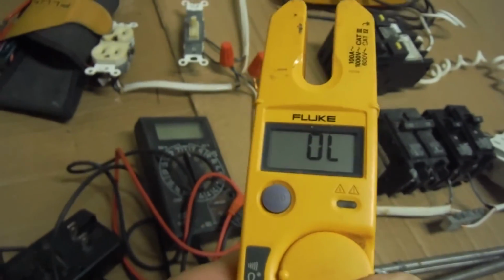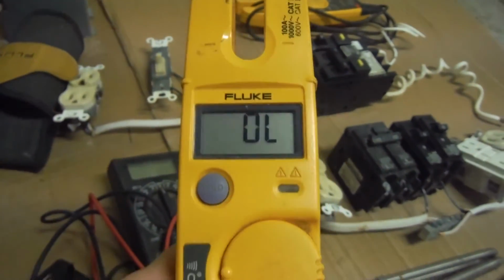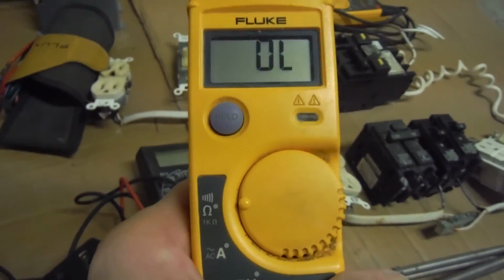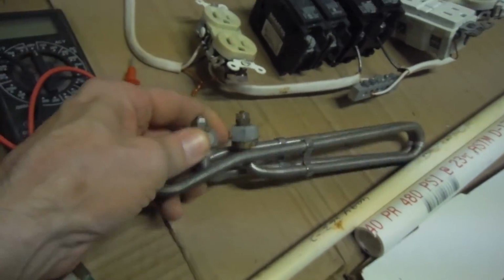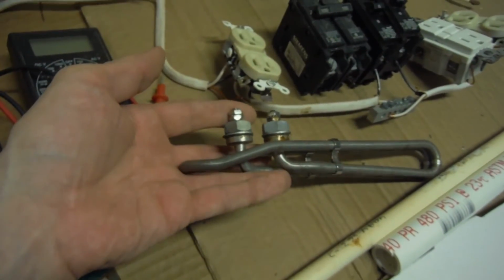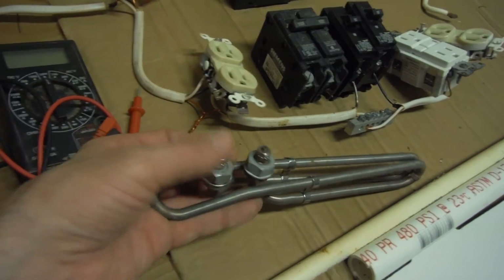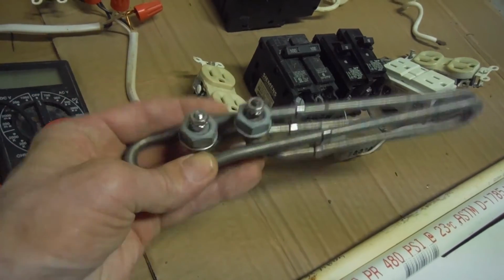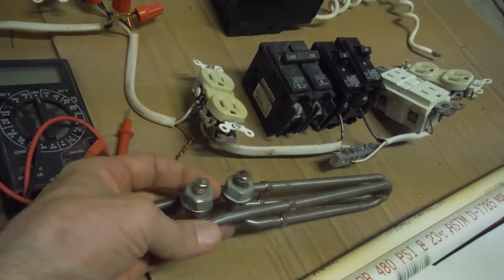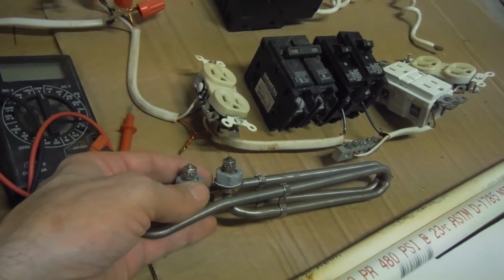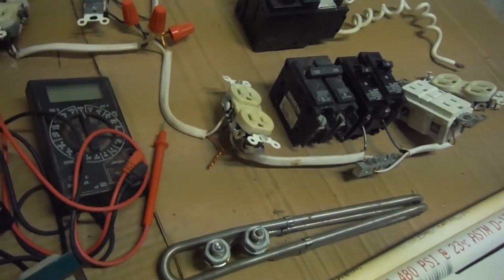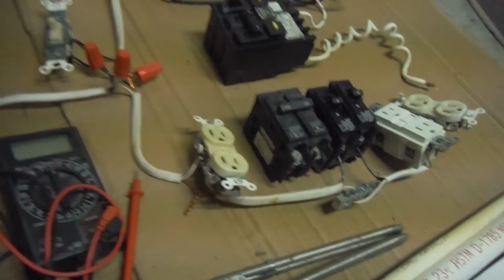You always, to my knowledge, I haven't run across an application yet where you run a test with ohms with the power on. You always turn the power off. Use your probes on the back. And that would be something you would do to, say, this heating element and check and make sure that it's got 12.5, 13 ohms, which is what it should have. I tested it right before, it's got 30. So it's definitely bad. Usually with a heating element, they're pretty specific. They're like dead on at 13, and if you're 14 or 12, it's dead. But, yeah. What else do we got here?